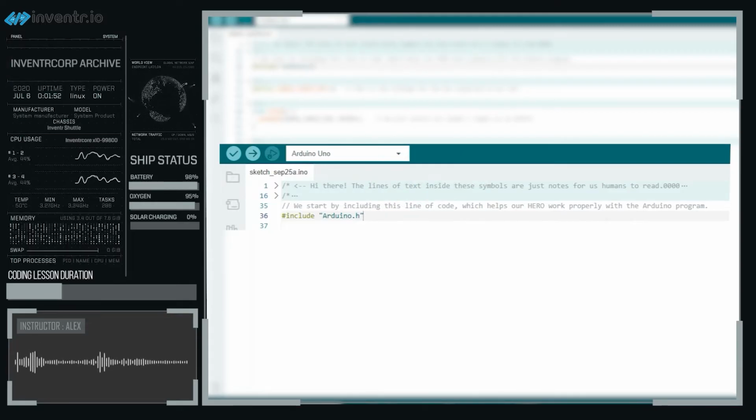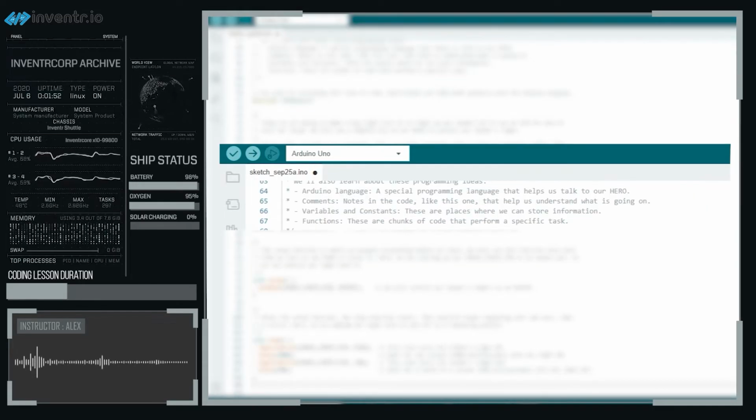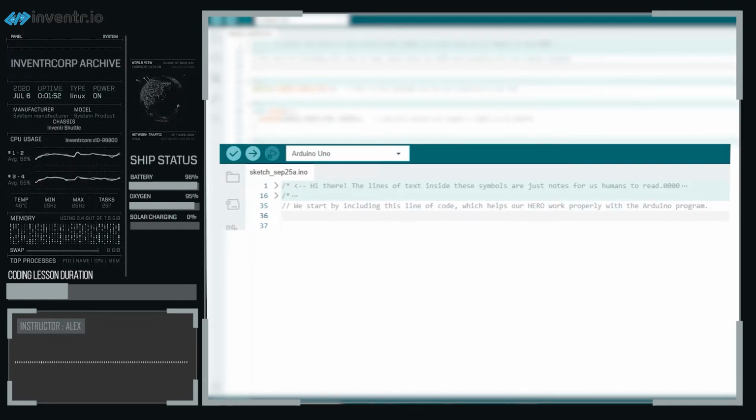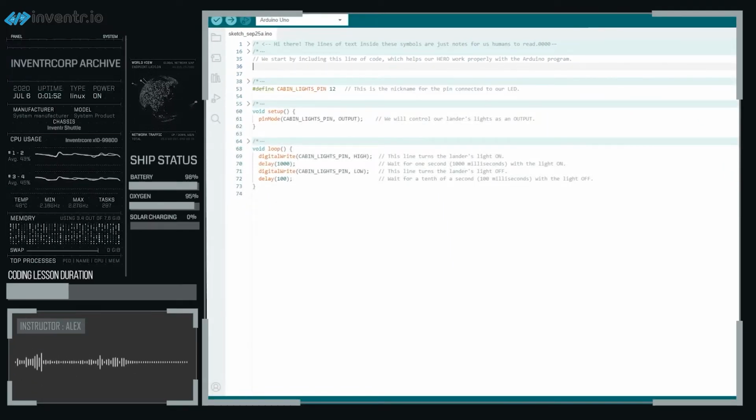Another thing I should mention is that I've added it in this case, but the Arduino IDE automatically includes a file called arduino.h for you. So if I were to go here and totally erase arduino.h and the include thing at the top, it would work the exact same. The Arduino IDE adds this in for us so we don't have to ourselves. Again, the only reason we have it up here is just to remind us that that code is automatically being included.